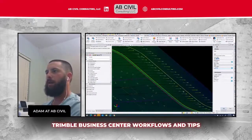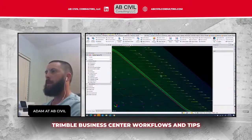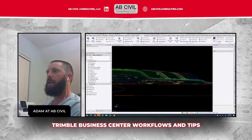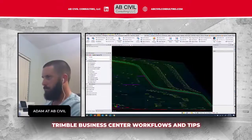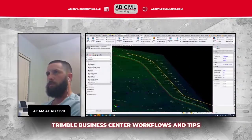So when I hit apply, oh, didn't want it to go to that layer. Just change it to sidewalk. So now you can see the sidewalk layer is floating up top. So same thing, I'm going to click on the line string, surface.